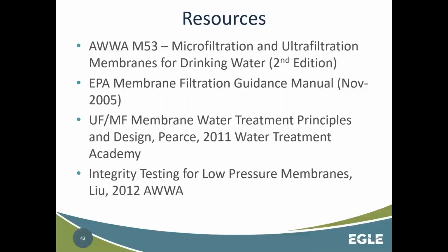I will point out when I personally got my crash course in membrane filtration, these two resources were invaluable, particularly EPA's membrane filtration guidance manual. That's free online. Just Google it. You can find it. If you're operating a membrane plant, it's a great resource. It has appendices that give example integrity verification programs. It talks about necessary operation and maintenance. It talks about the regulatory concepts.